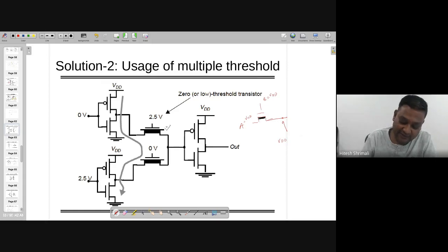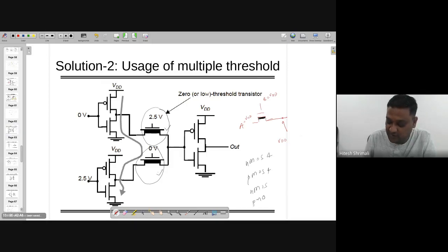So that kind of transistors can be used to implement the CPL logic as well as the pass transistor logic, so that there is no voltage drop. But you need to use these special transistors, like we are using NMOS 4, right? Then PMOS 4. There is availability of NMOS and PMOS. In the case of NMOS and PMOS, these are 3-terminal devices where the body is not connected anywhere, right? These are the 4-terminal.